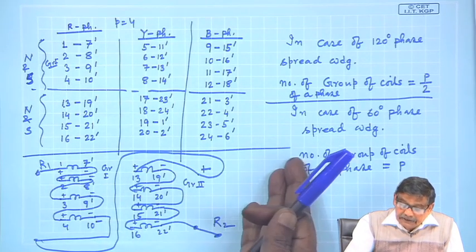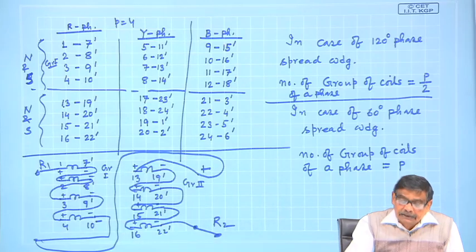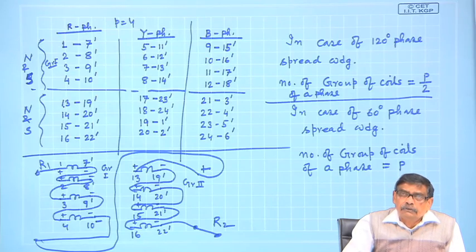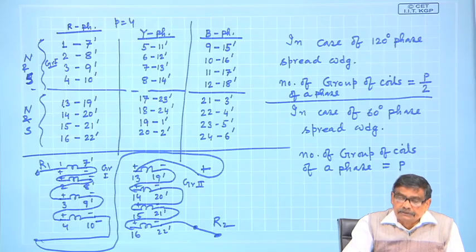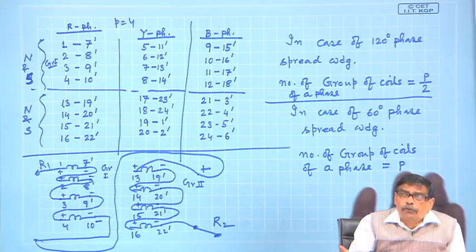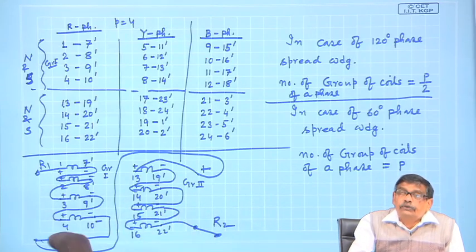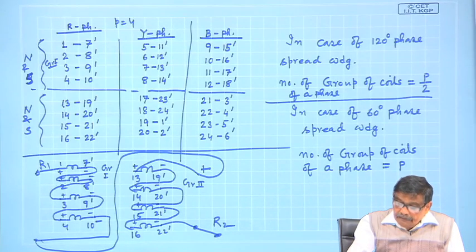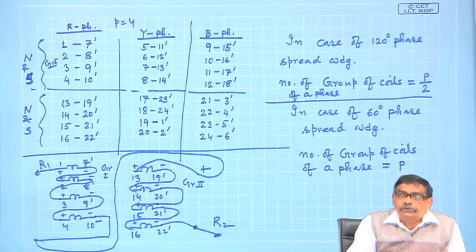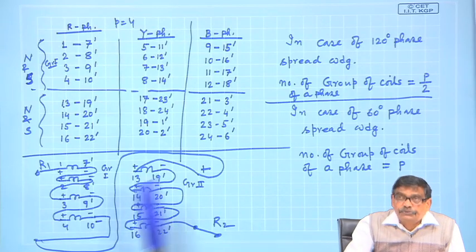But in this case the very distribution takes place based on under a pair of poles. So, over a pair of poles you have 120-degree allotted to R phase in immediate succession, next 120-degree. Therefore, as many pair of poles will be there, so many groups will be there. Understood. Therefore, if it is a 6 pole machine, you will soon discover there will be 3 groups.